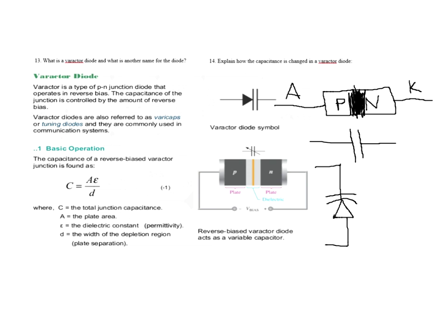Right here you have C, the capacitance of the diode, and over here my tuning control is actually a DC power supply. When I turn the knob of the tuning control, I'm changing the voltage applied to this diode. So when I change this voltage to a higher voltage, I have more capacitance here. A lower voltage here, I have less capacitance.